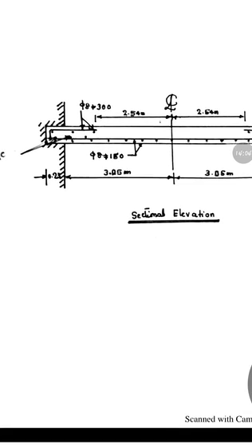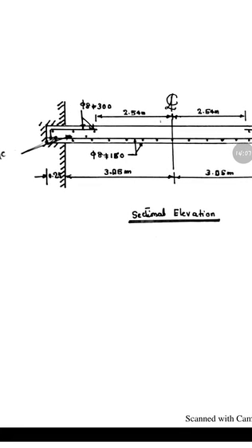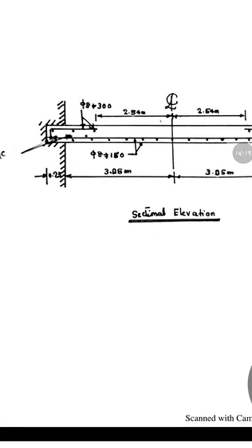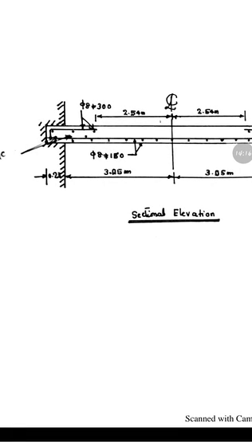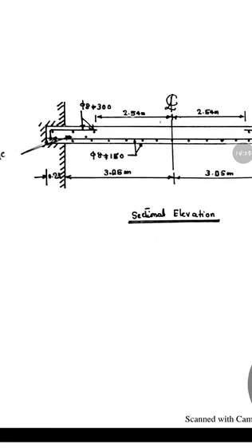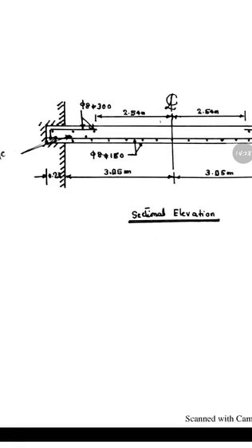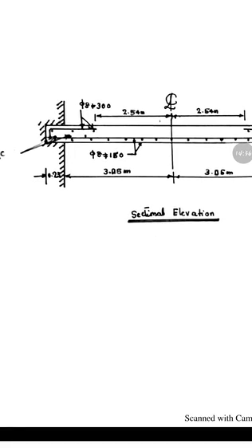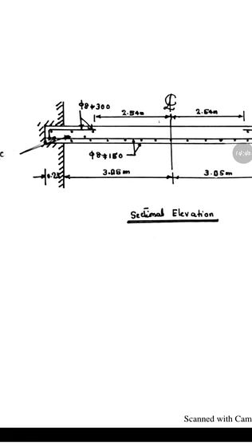Similarly, what about the ring bars which are shown towards the support? That is for the positive moment which is coming at M theta, the positive moment towards the edge of the slab. So for that edge we have found out 3 number of rings, that is 8 mm diameter at 188 mm center to center, placed at a distance of 2.54 from the support. So these are the rings which we have to show at the bottom plan.